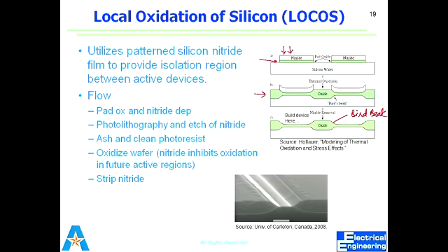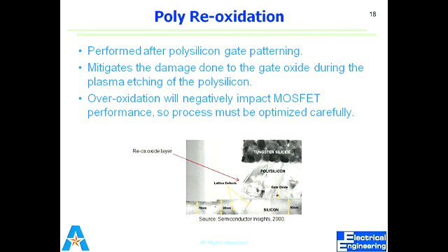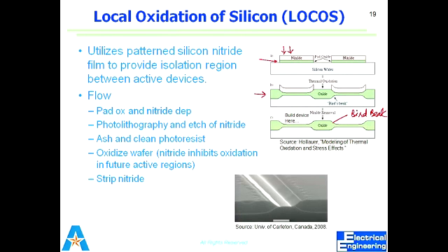In the gate oxide, we etch that oxide layer, but because it is over etched, it is not very accurate, so we need to deposit the polysilicon again. But make sure it is a very optimized process, because when we deposit the polysilicon again, it may happen that you have over deposited the polysilicon. So in the case of gate oxide, it should be a very optimized process, because your etching process and your deposition process need to be very specific.